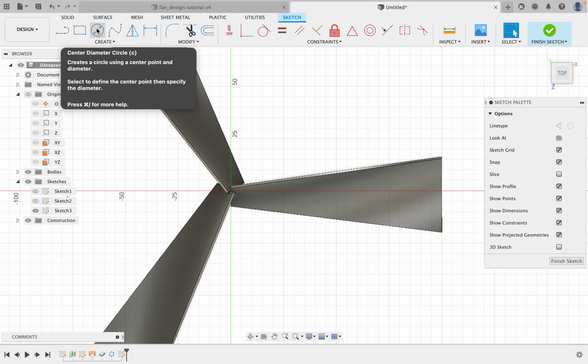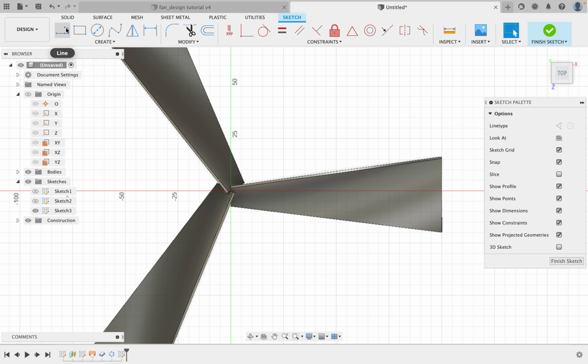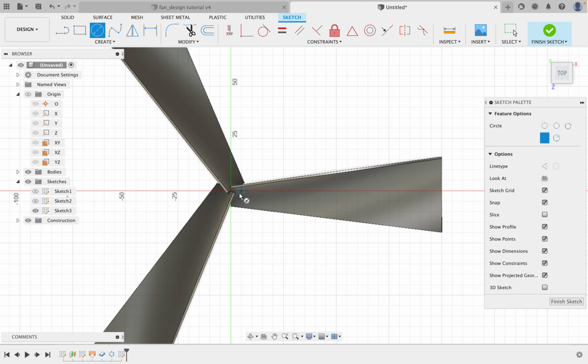I can now use my circle command. We have a couple of sketch geometry here, and we already used the line, we've used the arc. Another one is a circle. So we can use a circle, click the center or the origin, and move outwards. Remember, I'm not clicking and dragging. And I'm going to place this point anywhere. Good. Once you're done drawing your circle, right click, OK.